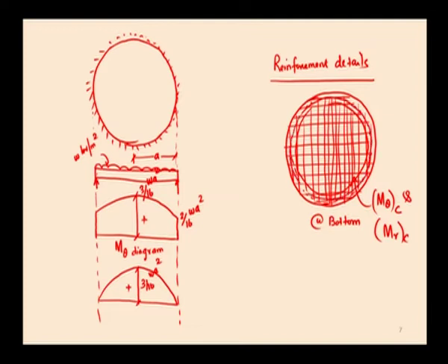At what distance does the reinforcement have to be provided? It has to be provided for a distance of Ld from the face of the support. The development length of reinforcement is pi into sigma st divided by 4 tau bd, as per IS 456. So, to resist this bending moment in the case of a simply supported circular slab, the reinforcement has to be provided